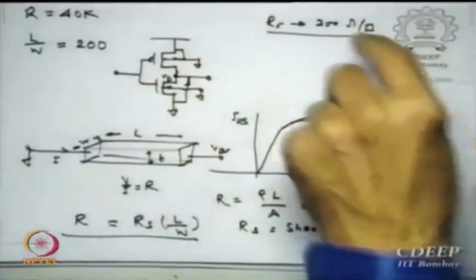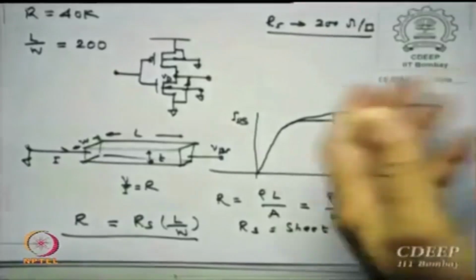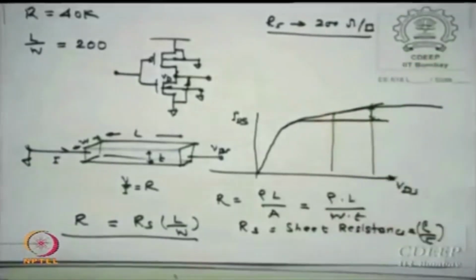Of course you can build this if you can increase this RS to 1000, 2000, 5000. Poly resistors are sometimes used in DRAMs, SRAMs, but then there is a special technology, additional money. If you invest, yes, R can be increased, and the length width ratio can be reduced.